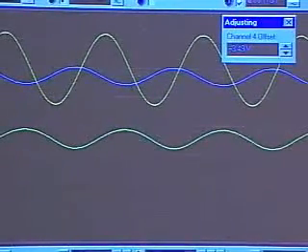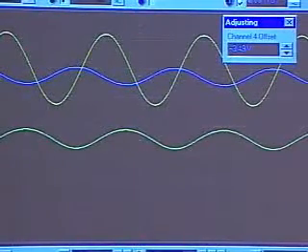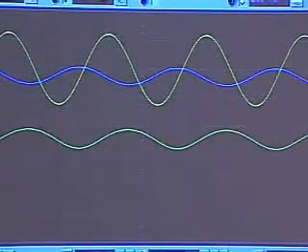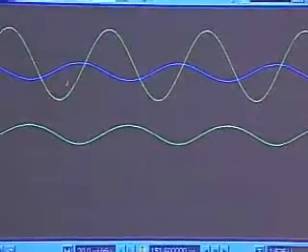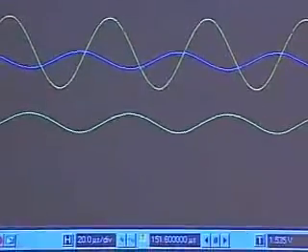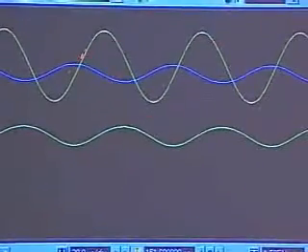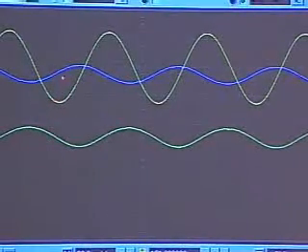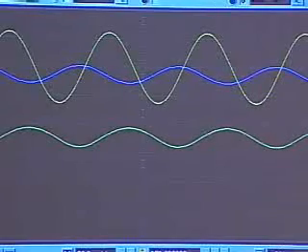Notice here, what we have been used to is for the amplifier, we get a complete inversion at the output. Inversion means a phase difference of 180 degrees for a sine wave, right? So this peak should have been here. But notice that there's a shifting of the peak.